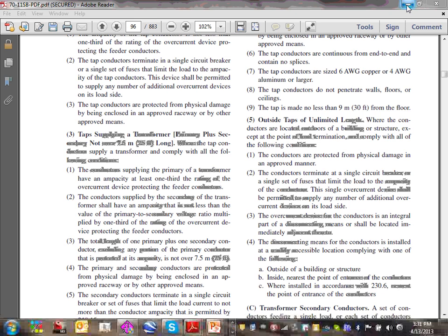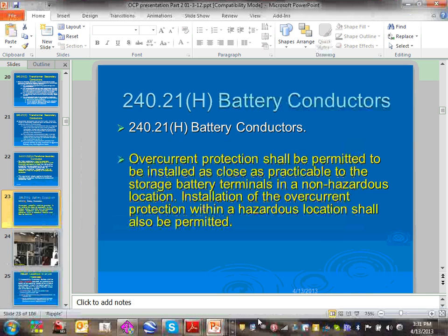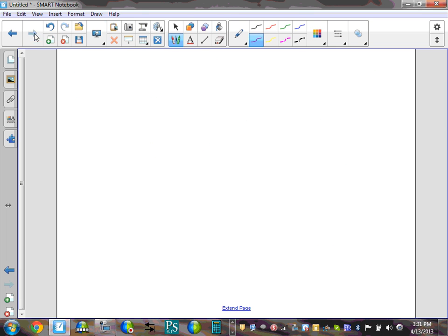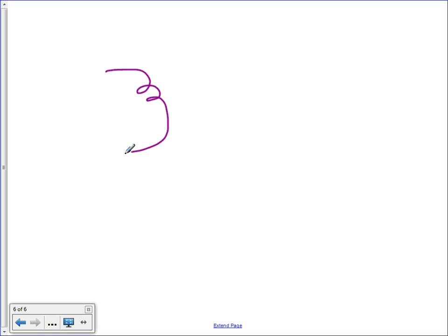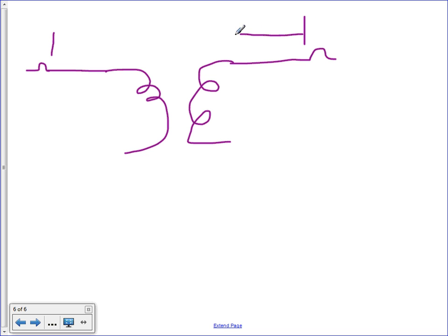So that's why, that's my favorite, the 25, because if you have a transformer this way, here's my transformer, and 25 feet, or 10 feet, the same way, guys, from here, and my overcurrent protection device is right here, and the distance from here to the overcurrent protection device right here is 25 feet. That's what they're talking about, the whole distance, 25 feet.